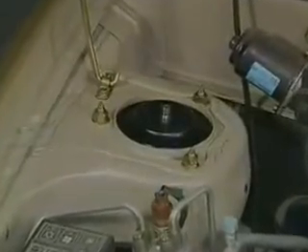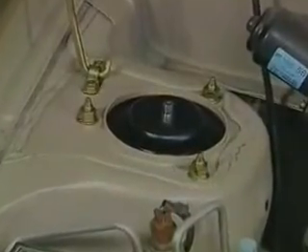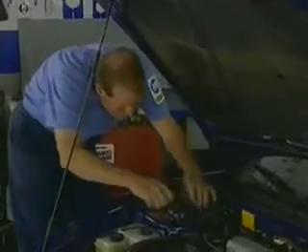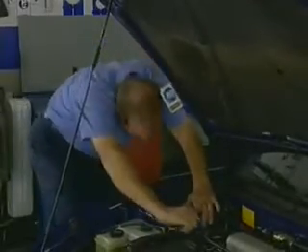If you're troubleshooting a caster problem on a front-wheel drive car, remember that some manufacturers do not provide for a caster adjustment on some of today's front-wheel drive vehicles. If the caster requires correction, an aftermarket kit is often available.